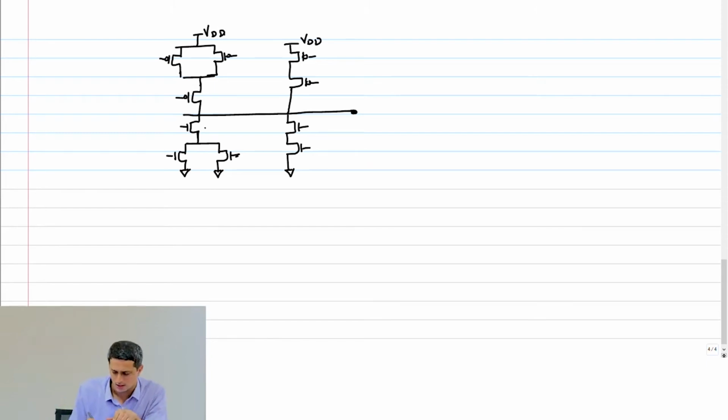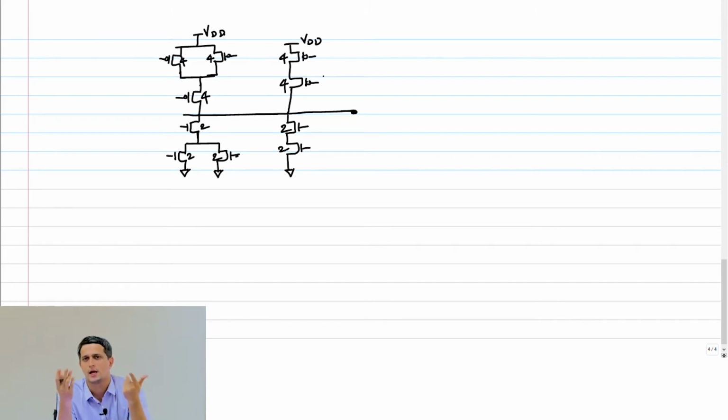Right? And what are the sizes now? Obviously, this is just 2, 2, 2, 2, 4, 4, 4, 4. Right? Now I have to assign the inputs. Because it's all interchangeable, AB plus BC plus CA, I could assign any input anywhere and logically they are all the same. So how do I assign the inputs here? How do I fix A, B and C to the transistor inputs?